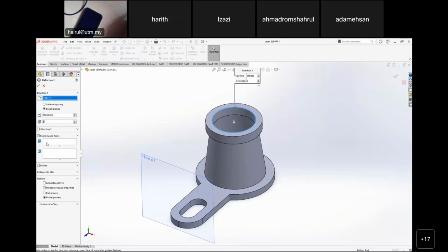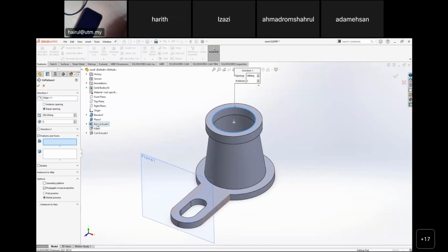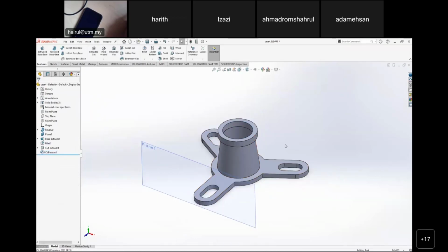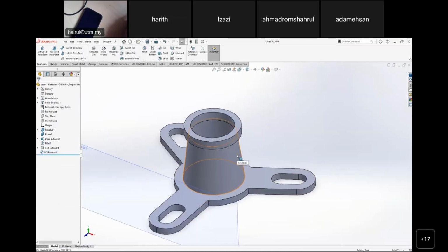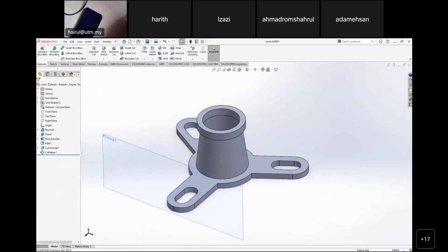Features are important. You can select like this. I have the arm. Can you select this portion of my arm, and another portion of my fillet, then another portion of my cut through? Or you clear all here, you select like this. And here select, I want the boss extrude, that is why I created the arm. This fillet, that is why I do the fillet, and the cut extrude, the slot cut through. Make sure you reset, then you have your features. Okay, see the use of features. This one will be in case 4. Case 4, we already saved it. So we have this thing, this arm.